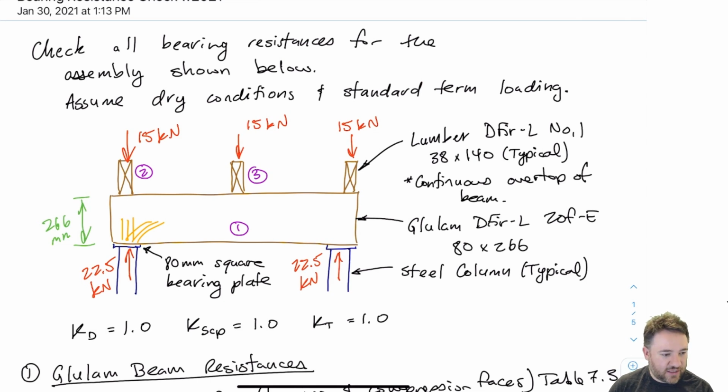But typically, if I was applying a load at the middle of a bending beam, then that is the area of the beam where the bending stresses are highest. So if I assume that the beam is probably designed for strength or moment at the center, then usually within maybe the middle third of a beam, those are probably the areas where we do have high bending stresses. But in this case, I'm going to assume that it's not in an area of high bending stress. The reason being just so that I can show an example of getting the proper KB from the table.